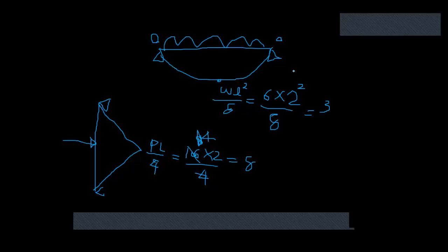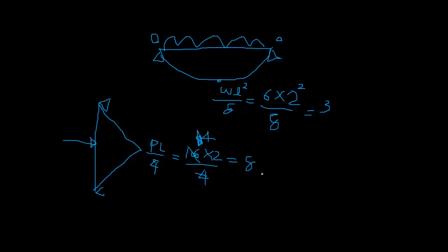Now we are at, yes, it's 8, right? So 16 into 2, 2 is the length, right? So simply supported, here it's 0, here it's 0. These are usually sagging, right? You remember? If you apply like this, your tension will occur on the bottom, so it's sagging. Usually the support bending moments are hogging, so tension on the top, right?